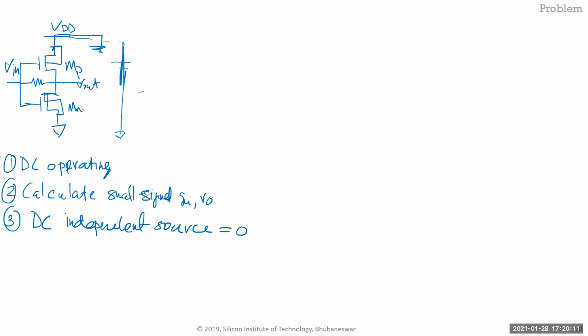All you do is you just take the transistor out, put the small signal model in. Take the transistor out, put the small signal model in. So initially when you start making the model, you actually keep the topology the same and then start making corrections, because you'll be inclined to say, oh, this is in parallel, let me just short it, and then suddenly your models will be wrong. Once you have a lot of experience, you can start doing that. But right now, just replace them as is.